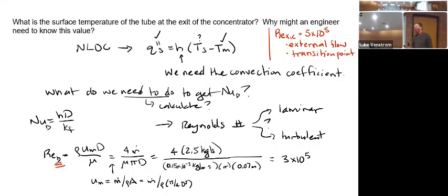We have a different number to use for internal flow. Remember what that number is? 2300, yeah, thanks, Nick. So this number is much, much bigger than 2300, and 2300 is our cutoff for the nature of the flow inside of the tube based off of the Reynolds number calculated on the tube diameter. So in this particular case, we're going to say this has got to be turbulent because the Reynolds number is much, much bigger than 2300, two orders of magnitude bigger than 2300.